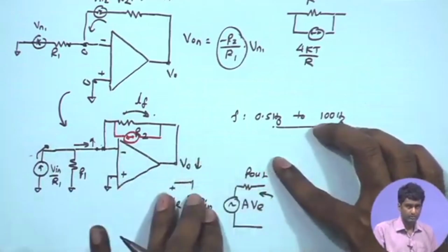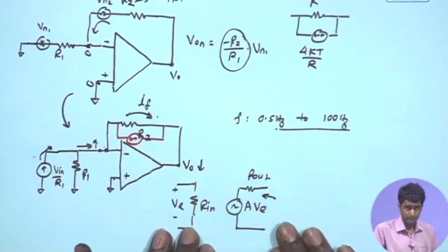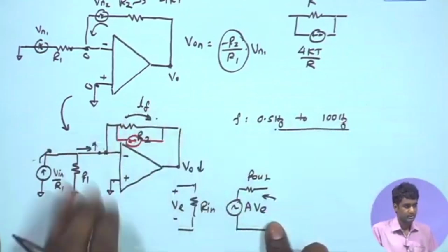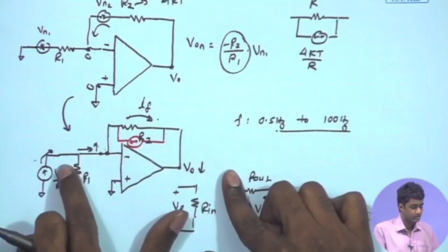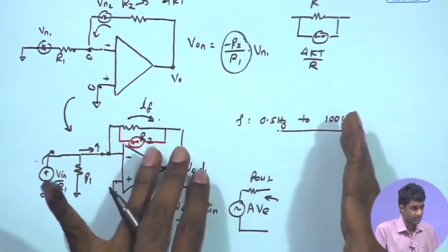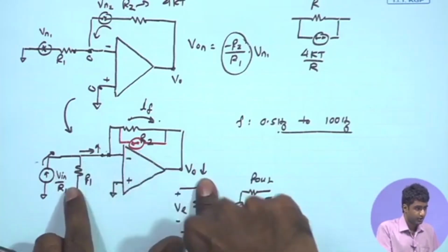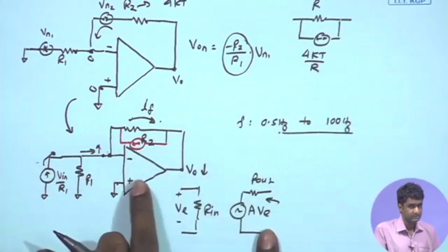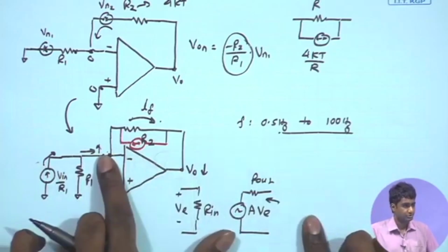So, this is how I would model an op amp, but I can implement any one of the 4 topologies of the feedback using op amp, and in that case the overall amplifier has to be modeled corresponding to the topology. So, here I can model this amplifier as a current to voltage amplifier. For that, we can characterize this amplifier. So, I can ask you to find out the overall 2-port network model of this amplifier as a current to voltage amplifier. You should be able to do that. You should be able to find out the equivalent input resistance, the current to voltage gain, and output resistance if I have to characterize this as a current to voltage amplifier. So, although I am using this op amp to build my circuit, effectively topology wise this is a current to voltage amplifier.